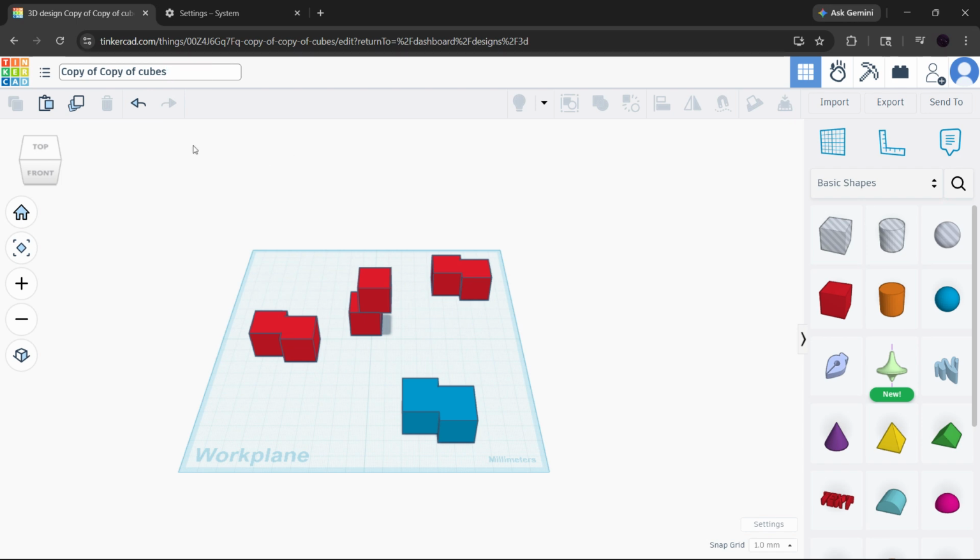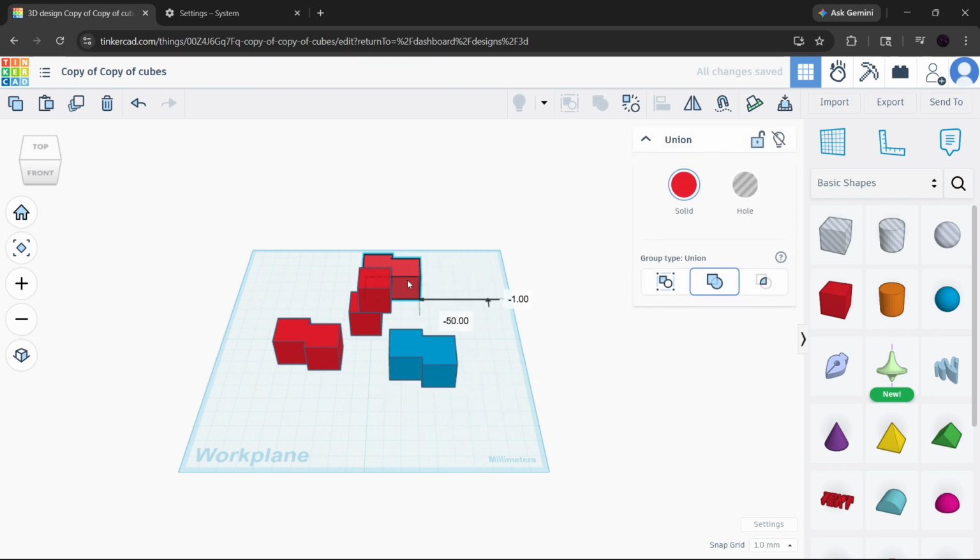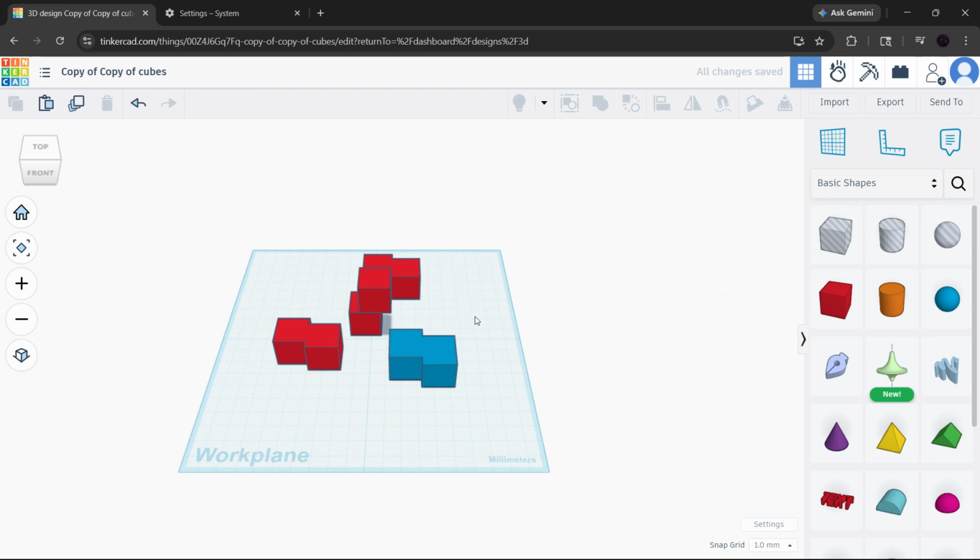So to recap, if Tinkercad says export STL failed, start by simplifying your model, removing nested groups, nudging holes by a tiny amount, recreating broken elements, duplicating the project, exporting in pieces, and checking your browser settings and file name. In most cases, one of these fixes will get your STL export working again.